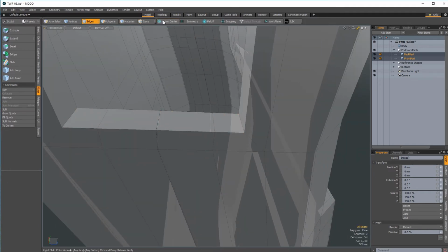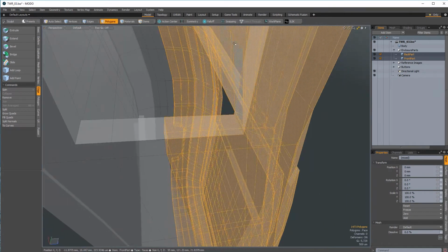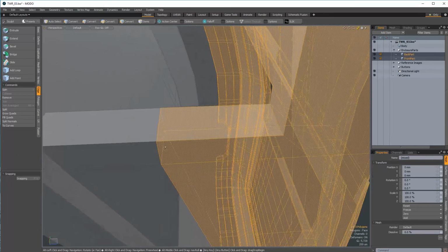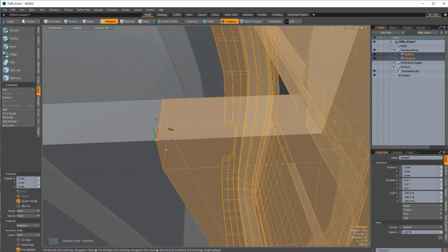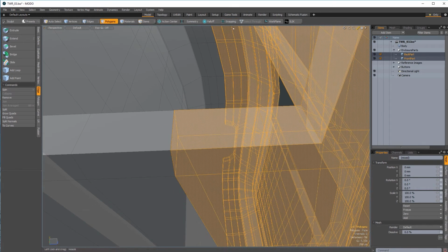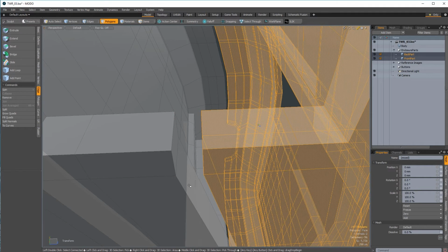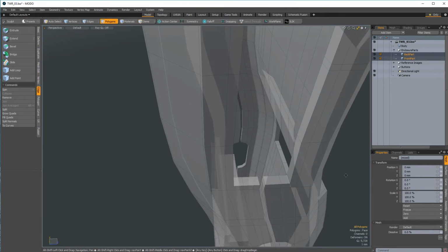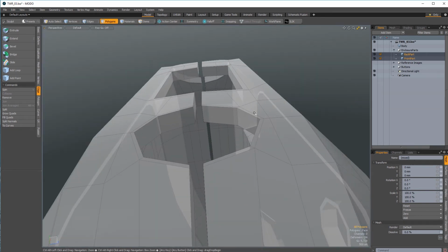Let's remove our action center, grab these polygons, turn on snapping, hit W for move, and I'll just snap to this vertex here, move it out just a little bit, turn off snapping. I'm also just going to move it even more. I'm going to move it 3/4 of a millimeter on the Z, and that'll set us up to create our lip groove fastening feature. All right, how are we going to do that?